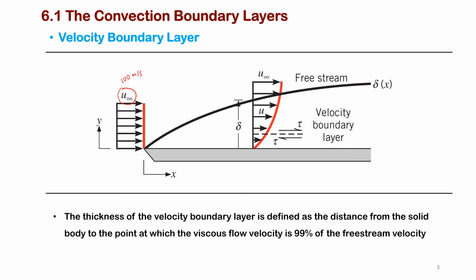And if we send this fluid over a plate, as shown here, we know from fluid dynamics that the fluid molecules that are just above the plate are going to stick to it. So there will be a no slip boundary condition. That means the velocity of the fluid at the base of the plate will be 0.